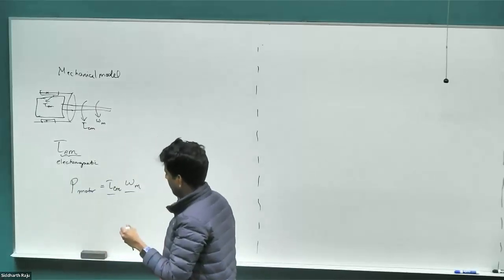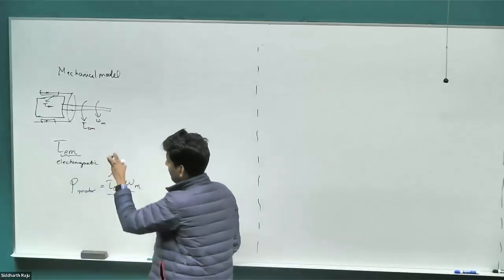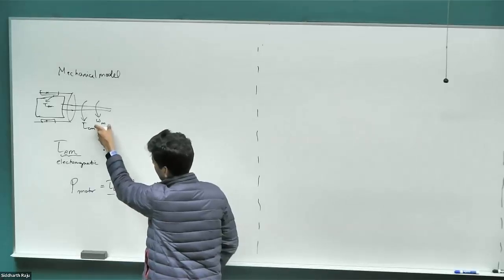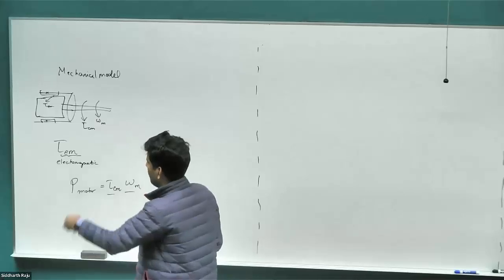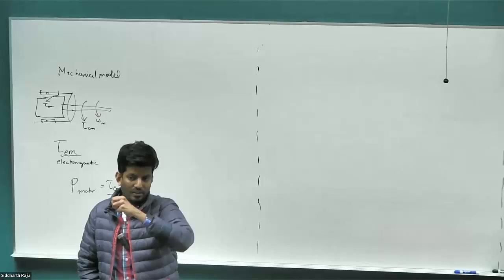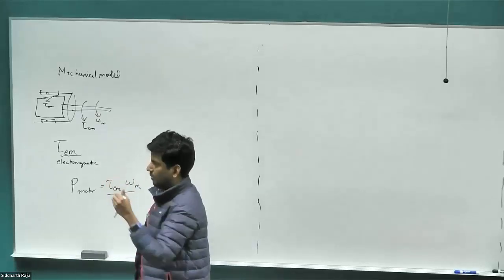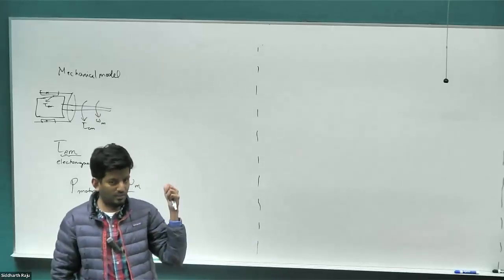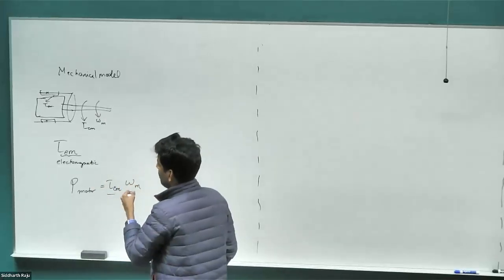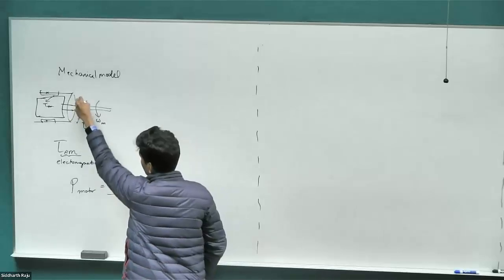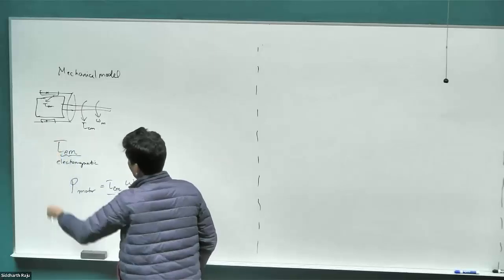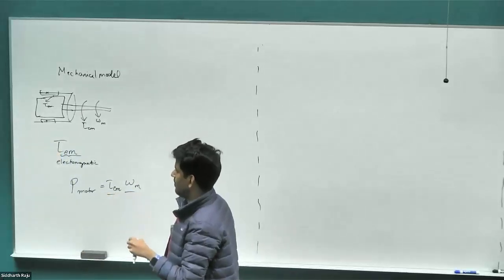And this is what we do in electric vehicles too, right? In electric vehicles, the direction of the speed is not changing. Speed is going to keep being in the same direction. But when you apply a brake, the torque basically reverses, and the speed cannot suddenly change because again, it's an inertial system. Similar to an inductor, where current cannot change, in an inertial system the speed cannot suddenly change. Otherwise, d omega by dt will go to infinity, which will be problematic. So we'll reverse the direction of the current, thereby taking energy back and recovering it so that we don't lose the energy in the braking system, right?